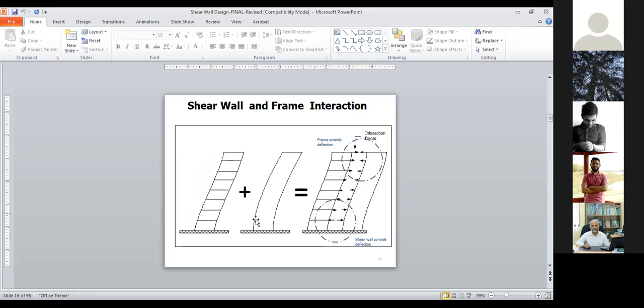your shear wall will control the deformation of the frame. So this is neutralized. Push and pull will happen here at the top and also the bottom. And when you come to the top, you will see that your frame, when you have the shear wall action, has the large deformation, but that will be pulled by the frame system. So through this interaction, your total deformation, and finally the moment at the base, will be reduced significantly. That is the dual system.